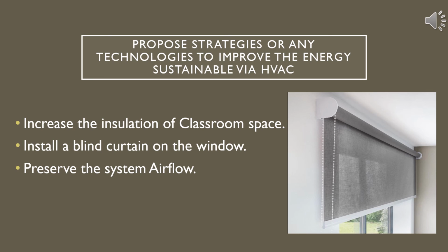And lastly, preserve the system airflow. It is important to keep the HVAC unit clean of dust and dirt in order to keep it running efficiently. Dust, grime, and debris can block up the system, making it work harder to push hot and cold air out.